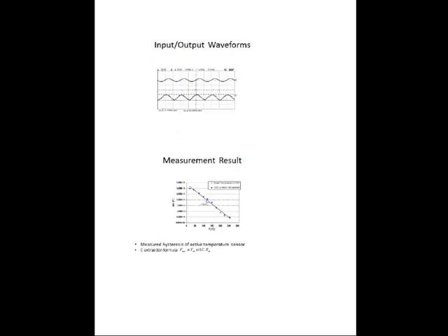And so this is basically the input-output relationship, just to show you. So we apply a voltage at 100 kilohertz. This is the input, this is the output. As you can see, the output is about 90 degrees lead compared to input.